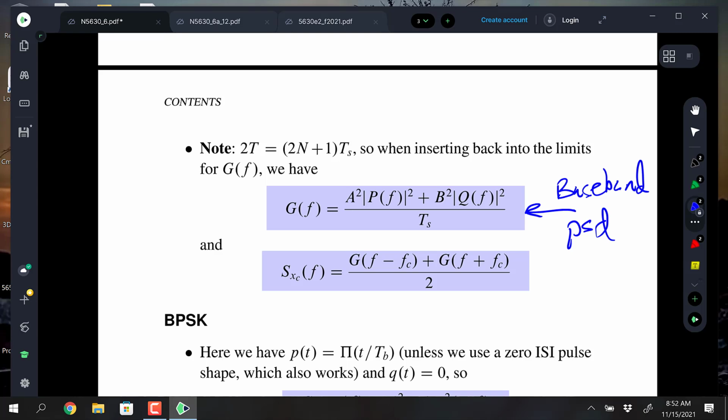And it also says that if the underlying bit rates on the in-phase is different from the quadrature, you'd just be superimposing spectral shapes, right? You might have a rectangle pulse shape on the in-phase, raised cosine on the quadrature, and it's all there. I mean, it's in the model then for the power spectrum.